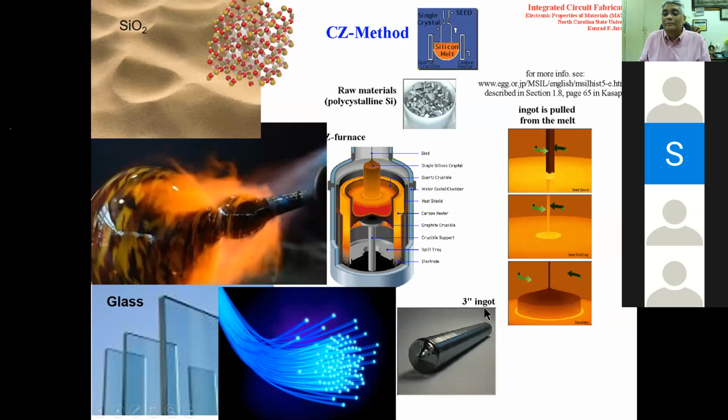feet long. Well, one interesting thing is the microelectronics industry survives because silicon can be made into these large balls of big crystals. This could be as long as 5 feet, and of course the technology is based on 8-inch and 12-inch wafers, and the process allows this to happen. But one such ingot, you imagine how much raw material is required. Even though you get it from silicon dioxide, a lot of raw material is required, right?